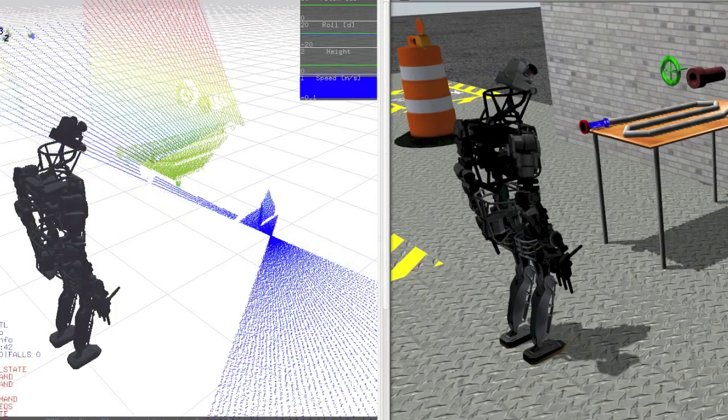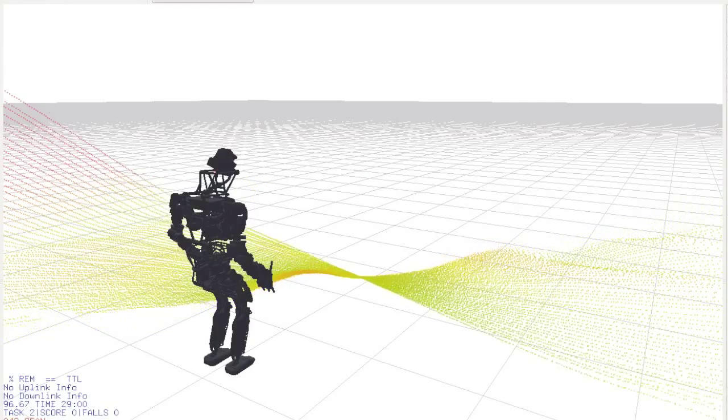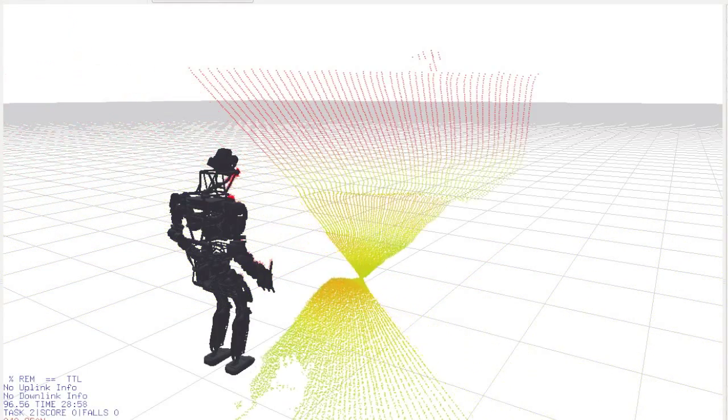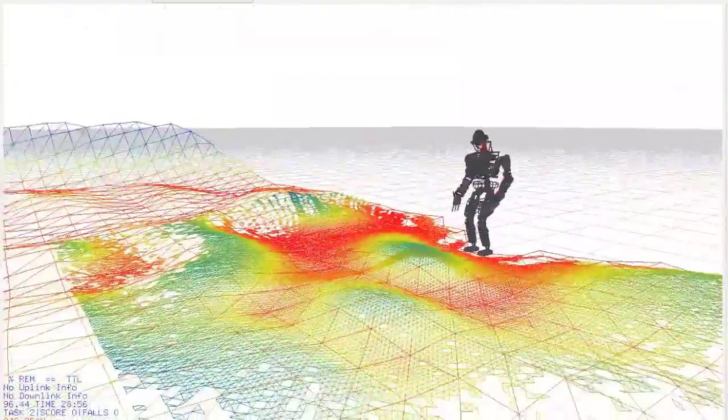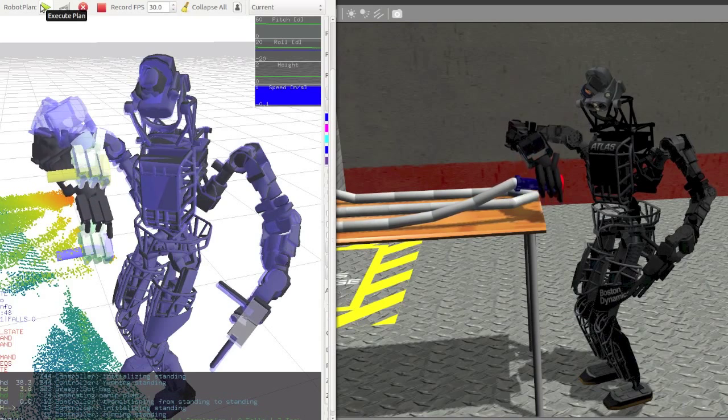To overcome these limitations, we integrated LiDAR data on short timescales to create a series of projections, depth maps of the robot's workspace, and height maps for footstep placement and situational awareness. Actionable objects of interest, known as affordances, were defined by simple primitives.